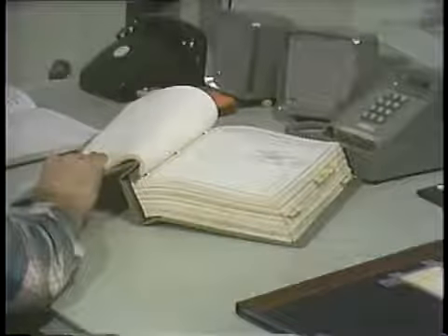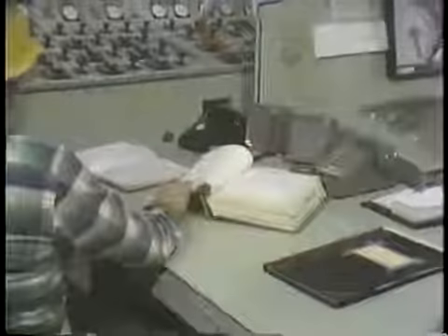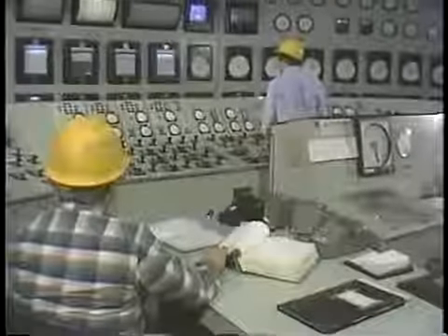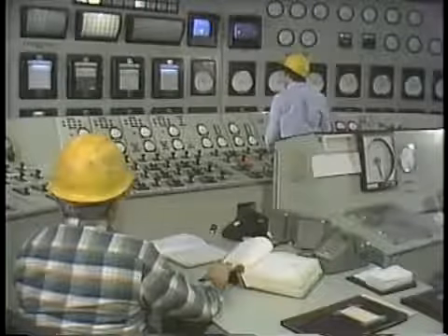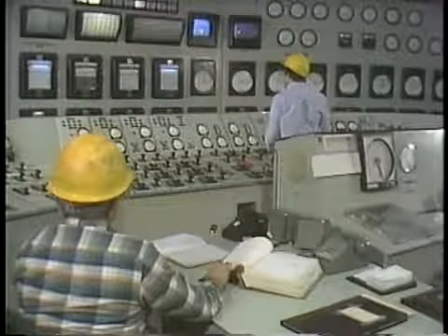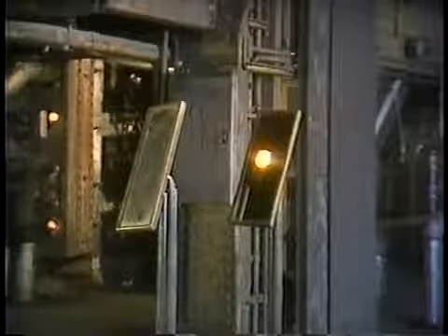As an operator, your best safeguard against a loss of flame is to follow your plant's procedures and carefully monitor control room instrumentation to make certain that all systems are operating properly. You should also make sure that television monitors, mirrors, and observation windows are available and indicating properly. Finally, if you suspect that there is a potential for problems with reliable fuel or airflow, additional igniters or warm-up burners should be used according to procedure.